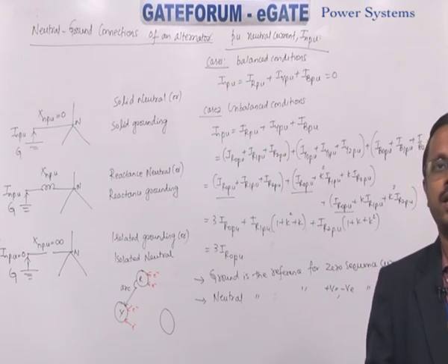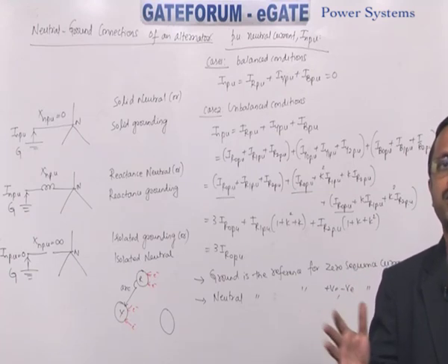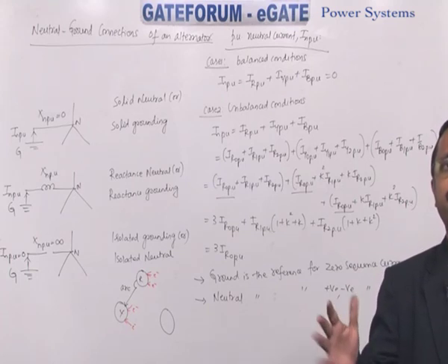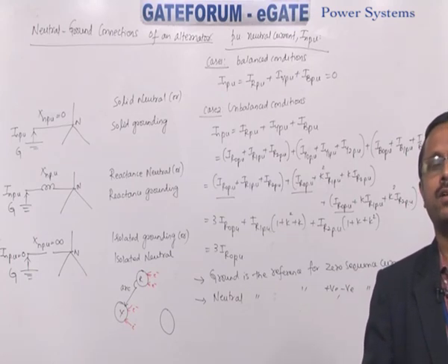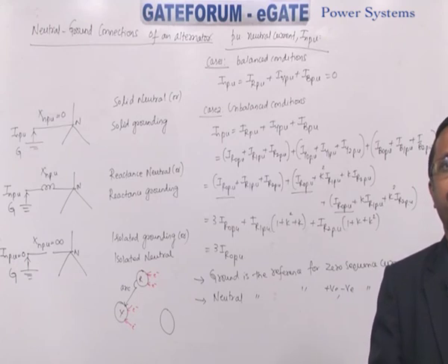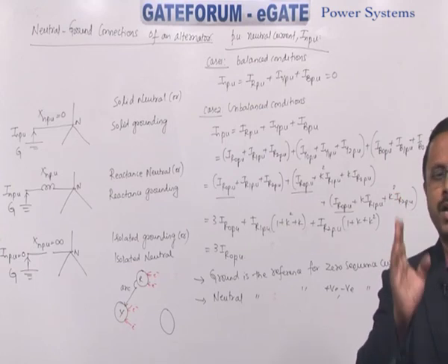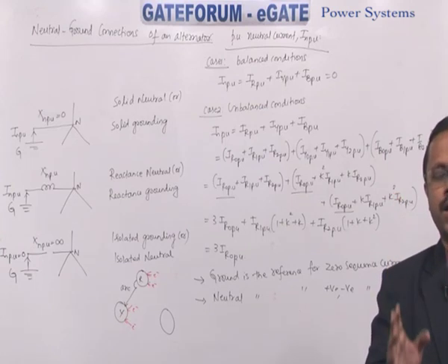That is correct, but for that unbalanced load, you don't have the zero sequence source EMF, you don't have the negative sequence source EMF. But EGR, EGY, EGB will be the same. Always source is balanced, load is unbalanced.